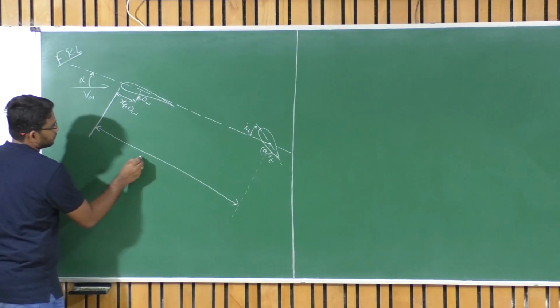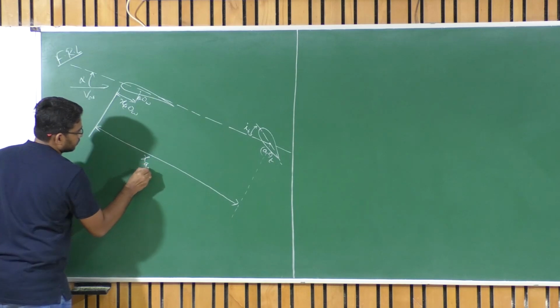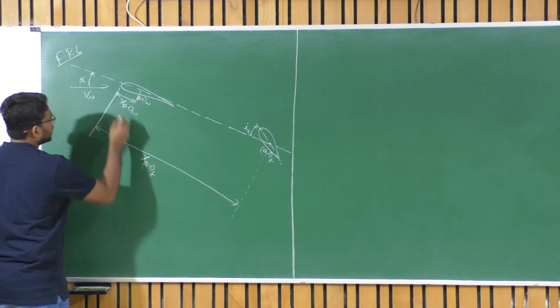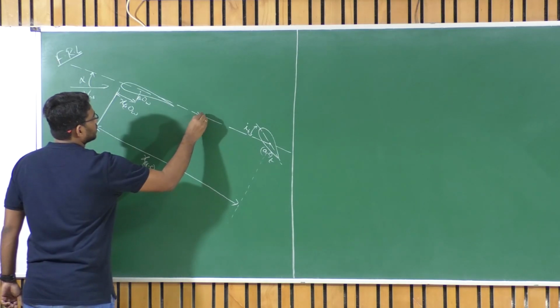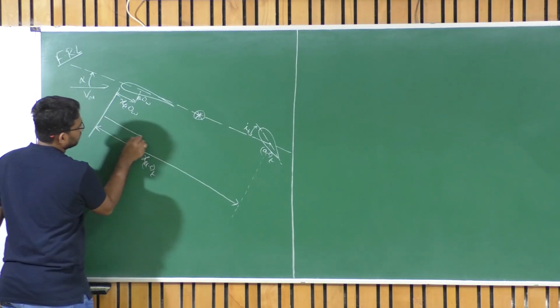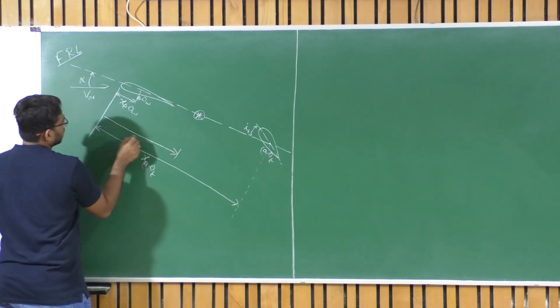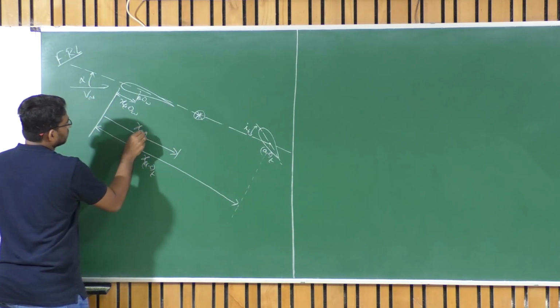XAC of tail with respect to the leading edge of the root chord. And now the CG of this combination is assumed to lie somewhere in between the wing and tail, and the corresponding location is XCG of this combination.